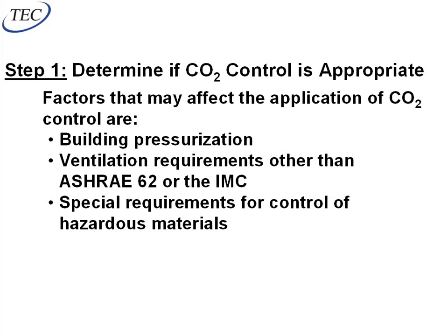What happens, though, is in practice, when those people aren't there, and I'm deciding if they're there, whether they're breathing or not based on their CO2 exhaling, if they're not there, then I get to modulate my ventilation air back. So some people get confused, and they think that we're going to take the ventilation code air and then modulate it open from there. That's not the case. We're taking the code ventilation air and modulating it closed from there, providing less ventilation air. So I don't have to design any special equipment because I'm not going to provide any more air than I normally would have on a normal job. Just I'm going to provide less during some times of the year.